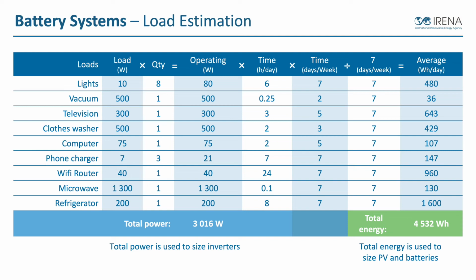But we want to be as accurate as we can. The problem if we're wrong in estimating our loads here: if we estimate too high and we assume the loads are bigger than they actually are, it's not really a problem from a design perspective, but it becomes a much more expensive electrical system. So if the system is oversized, it's more expensive, but it's going to work great.